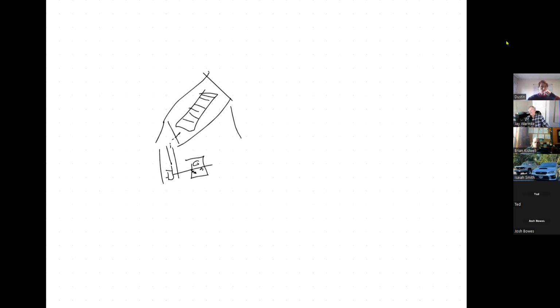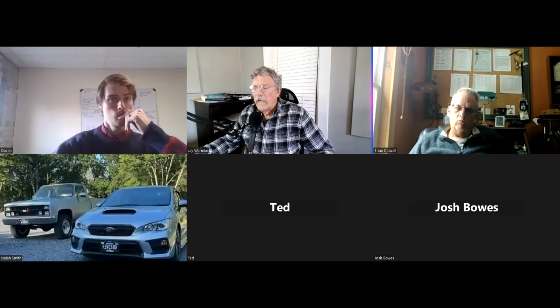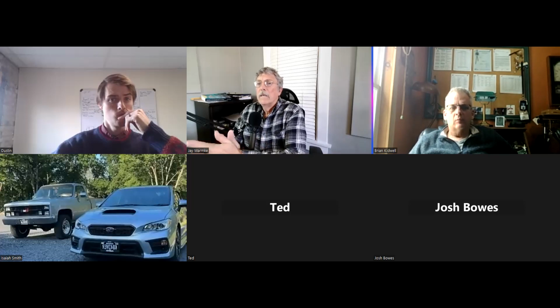So those meter boxes now, those utility disconnects, are required as part of the 2023 NEC. So if you do a substantial electrical upgrade, your utility might say, "Hey, you gotta put in a new meter box," because every time you do a substantial change, you've got to get it up to code, and that's going to be the new code.